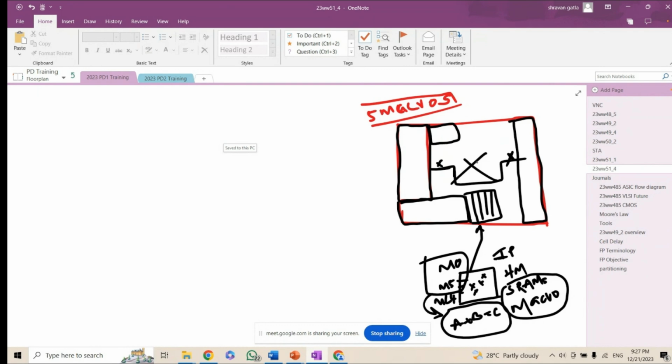Because if you place it in the middle of the core area, let's say one signal needs to be routed on M1 only, okay, M1. But what happened: you placed the macro here, but that M1 is already blocked. The macro already used that M1 layer, or else the track, we also call it the track, is already used by this SRAM, the macro.